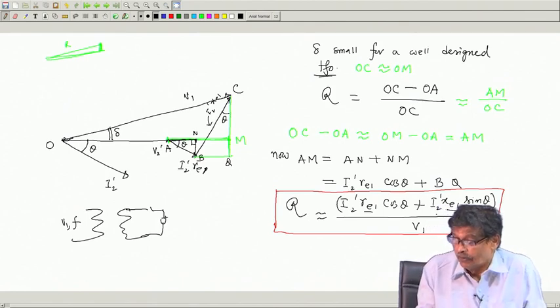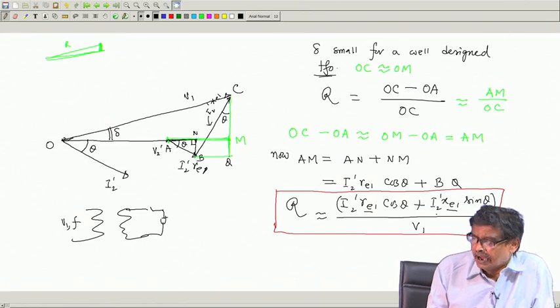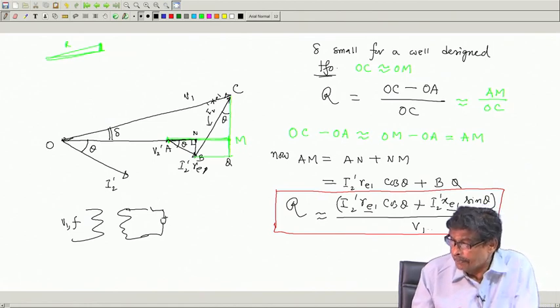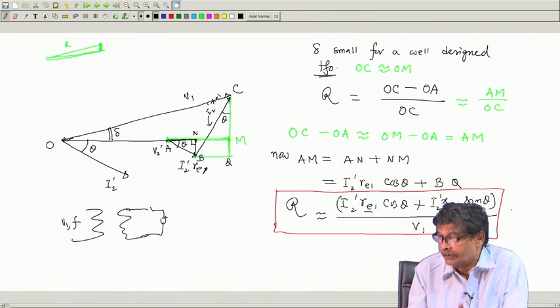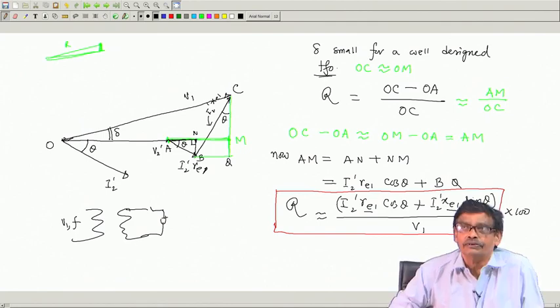You ask, what load have you connected? It is delivering rated current at what power factor? 0.8 power factor lagging. Then on pen and paper calculate regulation, into 100 if you want percentage regulation. So, you are predicting regulation without actually loading the transformer, that must be understood.